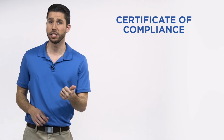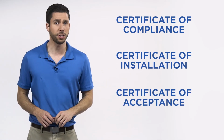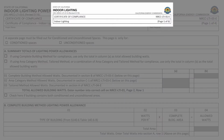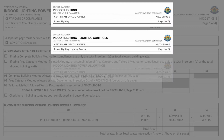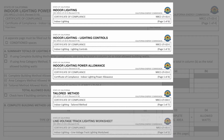There are three types of forms that are needed: the Certificate of Compliance, the Certificate of Installation, and the Certificate of Acceptance. First, let's look at what's needed for the Certificates of Compliance. The design team and responsible person are required to identify all required equipment and systems necessary to meet Title 24. They also need to identify systems that require acceptance tests. The certificate must be completed prior to applying for a building permit.